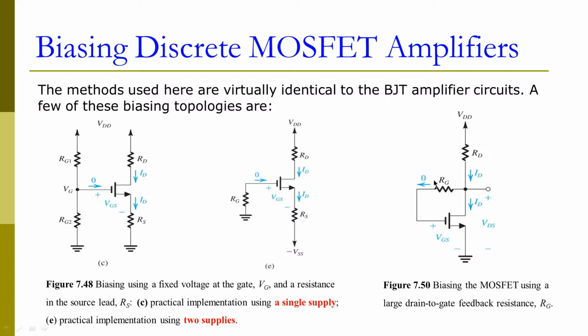The last one actually we have discussed before. In this one, we connected the drain and the gate through a larger resistor. In this way, we can guarantee the transistor is working in saturation mode if our VDD is large enough, that is, our VDD is larger than VT.